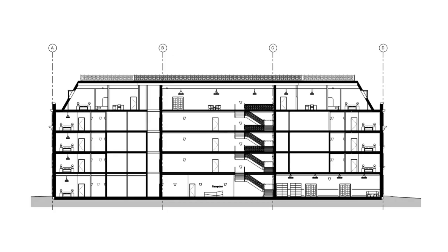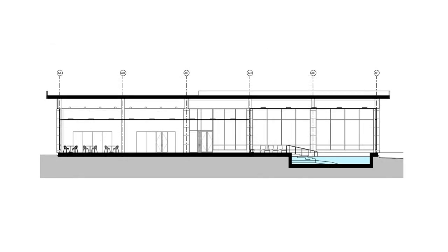Section views show a vertical slice through the building. They're useful for showing the vertical orientation of the building and also how the structure will work. The components being cut by the section are often shown in bold line work or with a solid fill, and the components that are beyond the cut line are shown in a lighter line work to represent their elevation.